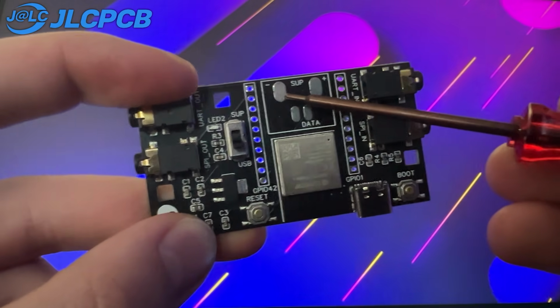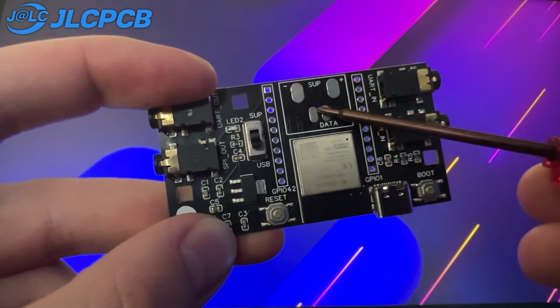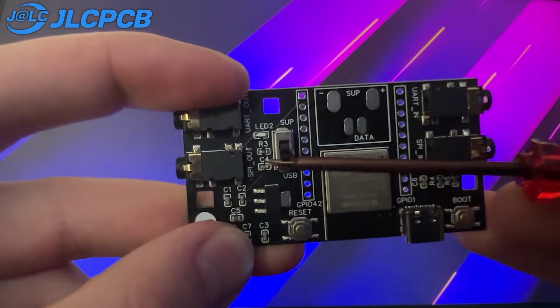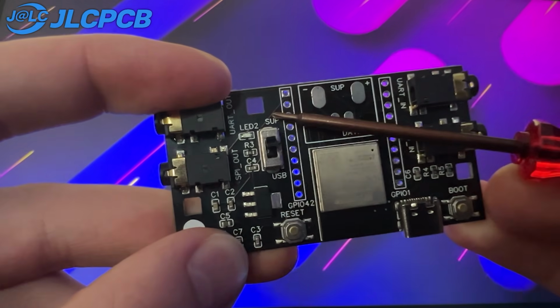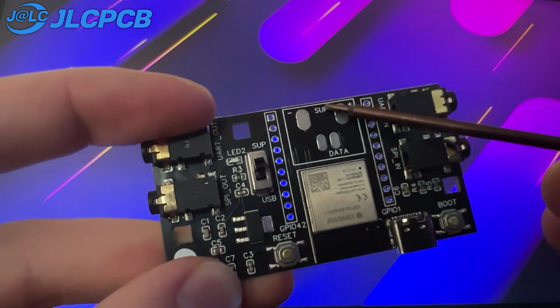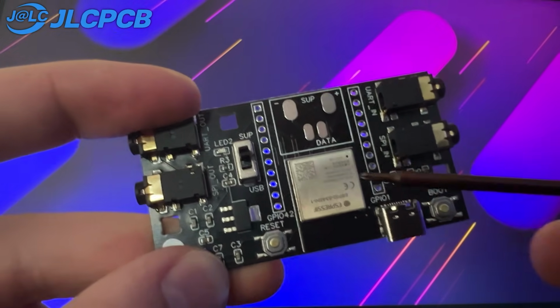Speaking of power supply, we have some pads up here that we can solder our power supply wires to, as well as the data wires for our LEDs. And then we have a switch here that lets us switch between supply power and USB power so that our lines don't get crossed if both the power supply and the USB port are plugged in at the same time.